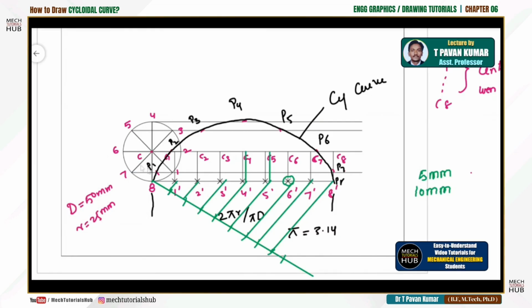Fine. Divide the circle, whatever the diameter given, draw the circle first. Calculate pi d distance. Alright. Now draw a tangent line of that distance, that much distance. For example, pi is 3.14 and the diameter given to you in the question is 50 mm. Then overall thing becomes 157. So the distance from here to this point is going to be 157.